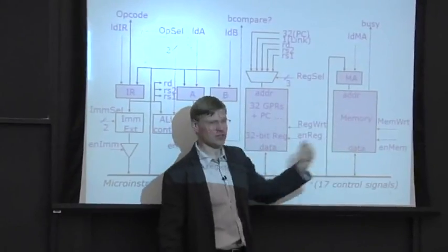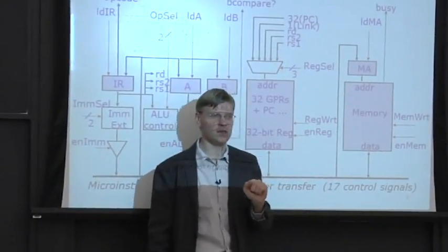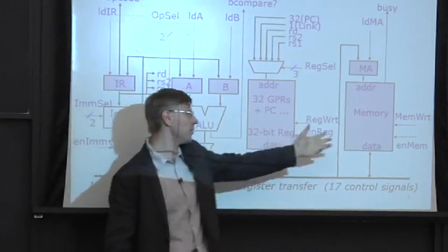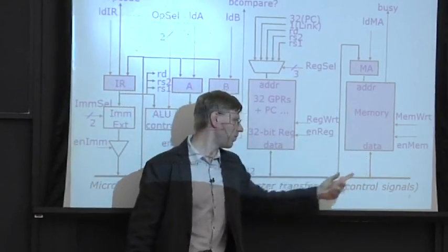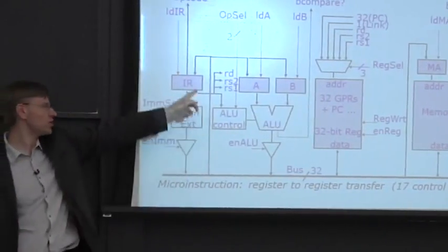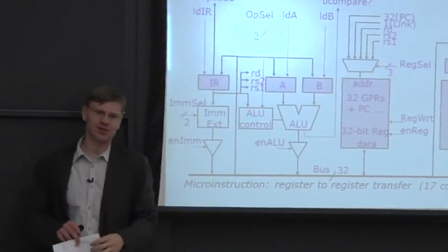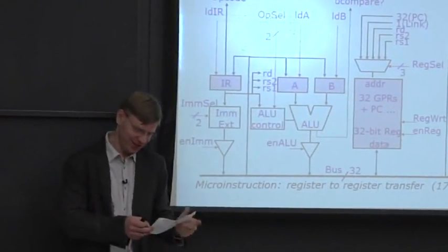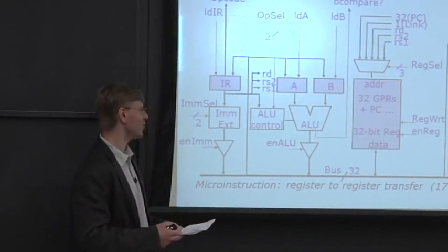we're going to fetch the instruction we need from the data memory and the instruction memory. So that is going to get forced onto this bus, and we're going to take it and latch it here, or register it, into the instruction register. So at this point, we fetch the instruction. OK, that's done a fair amount so far.